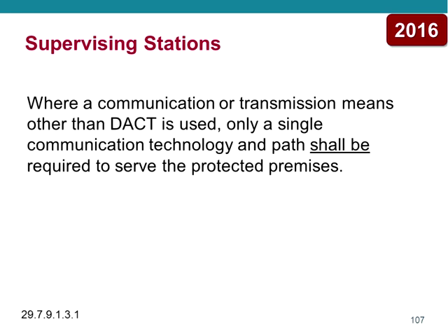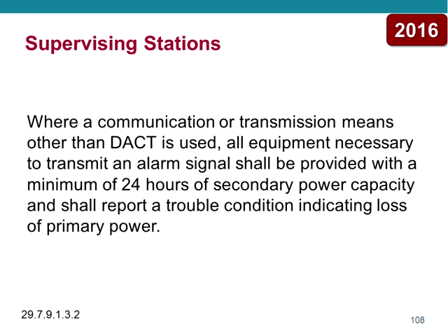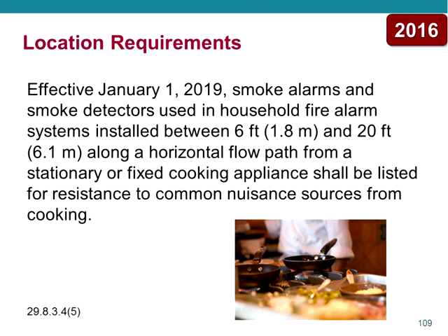Again, remember, if you are using any communications means, you have to have 24 hours of power on that communications means, from basically the panel all the way to the service point of that communications technology. Again, that's just what I said right here, 24 hours of standby power, and it has to indicate a loss of power. So you're going to get yourself a UPS, and that UPS is going to be monitored for loss of power.